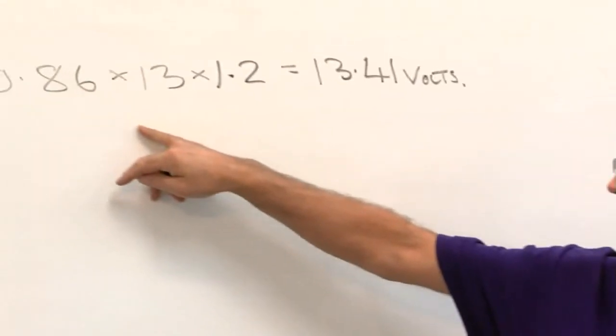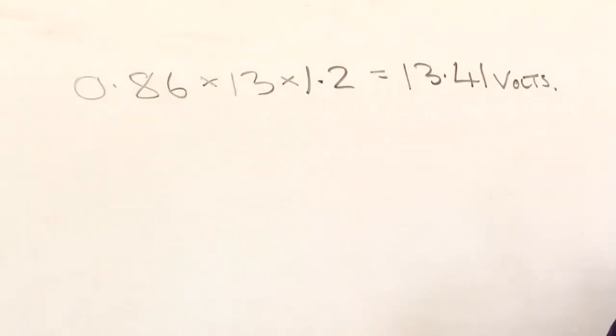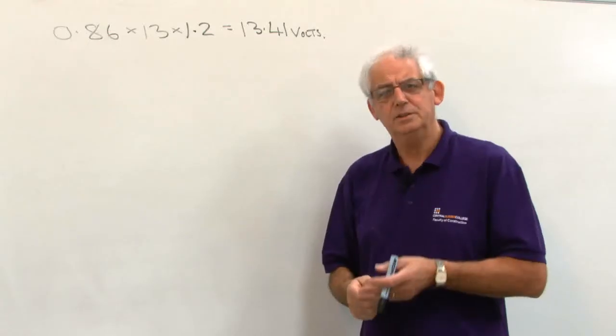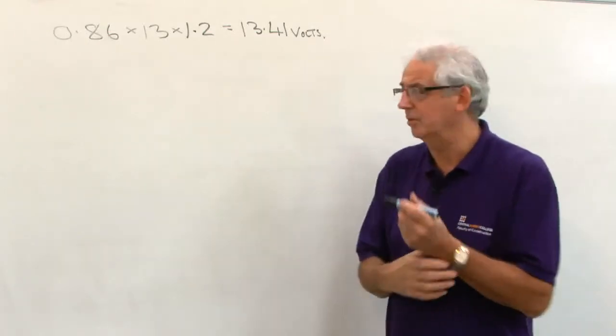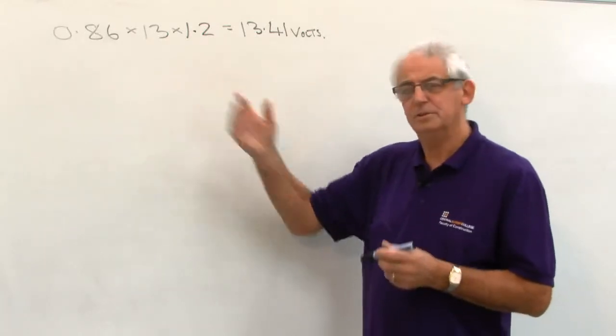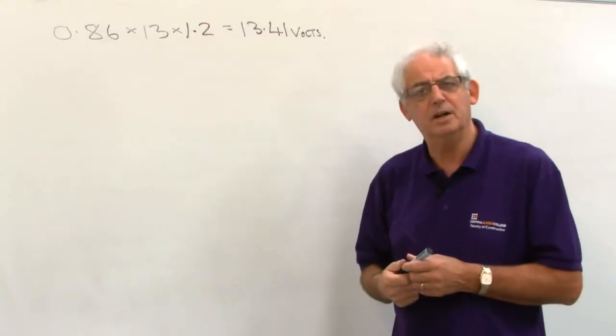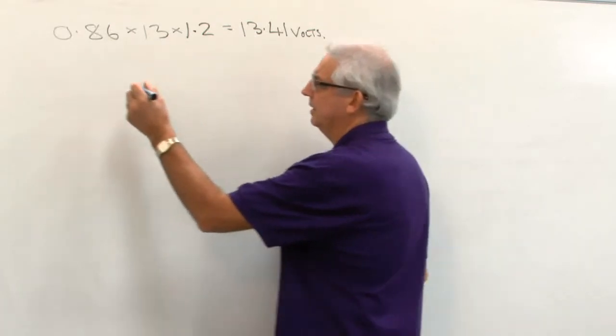But again, we also know that this R1 and R2 value is made up of a 2.5 line conductor and a 1.5 CPC. So using the process that we used before, we can calculate the resistance of our line conductor only. Simple process.